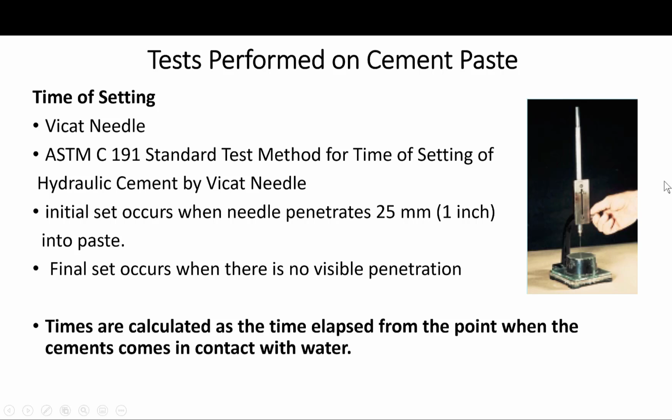As you can see here, here's the apparatus, and it's molded in this mold right here. Here is the paste, and you just release the needle, and for initial set, measure the penetration. For the final set, no penetration.